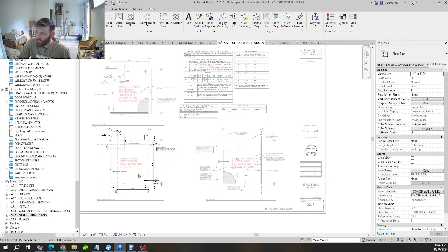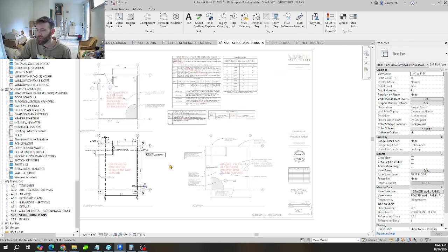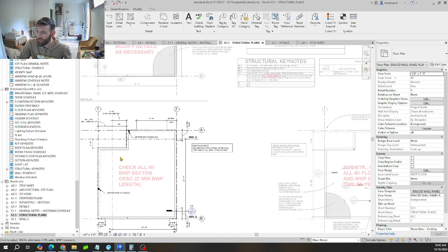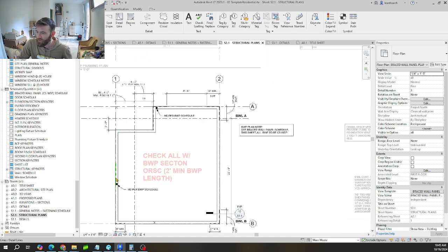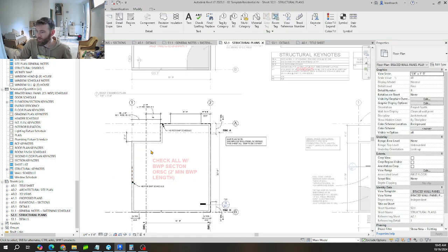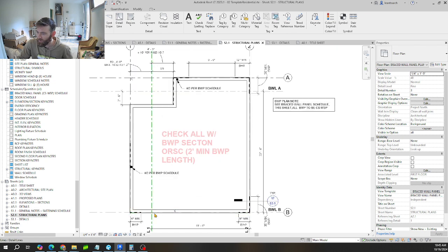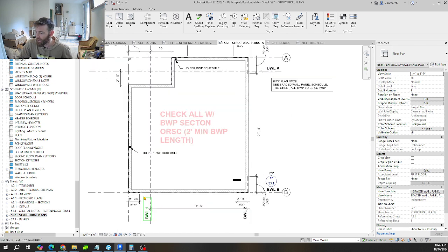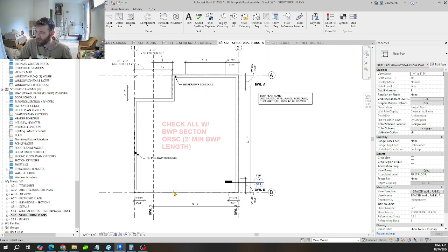Choose your brace wall panel type and figure out how much space you need on your walls. So you really do need to have some sense of this brace wall panel length requirement before you place your windows. But to be safe, at least give yourself 2 feet from your window to the edge of your building.